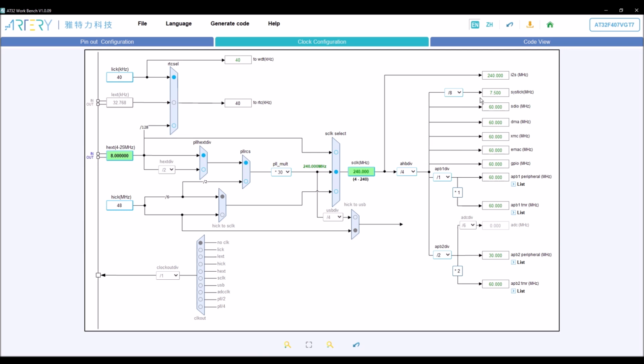In the clock configuration, I've used 2 frequency dividers so that the SysTick timer runs at 7.5 MHz. This could potentially be a disadvantage since other peripherals operate at a lower speed. The reason for reducing the timer frequency is to achieve longer delays, as I'll explain next.